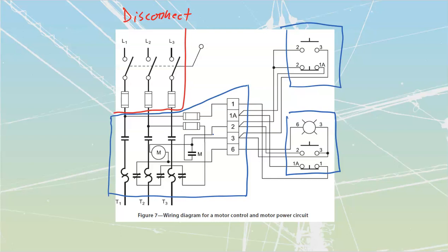Now that we've done that, we're going to start by identifying where this control circuit gets power. And then we're going to track a line down from there. So I take a look over here on line 1. I see you've got a little stinger taken off line 1, taken to a fuse. That's where I'm going to start my diagram. I'm going to start by labeling this thing because I don't have a label on it yet. We will give it an actual label, F1.